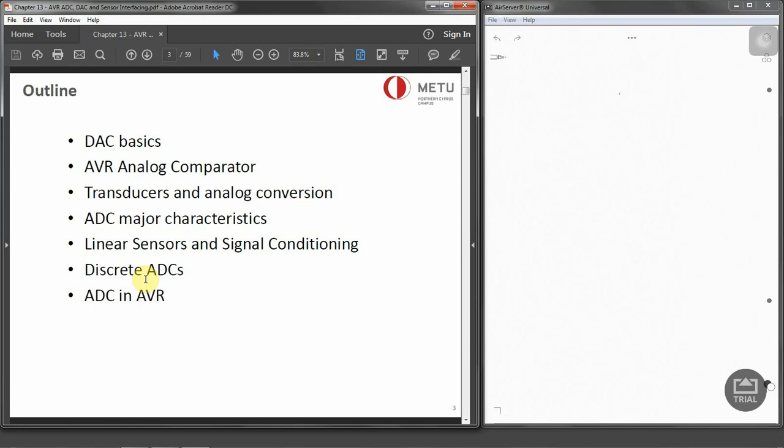These two are generally comparable to each other, but most integrated circuit DAC devices use the R2R ladder version, because R2R offers higher precision compared to binary weighted. And when we consider digital to analog or analog to digital converters, one of the most important judging criteria is their resolution, because resolution gives more accurate results.